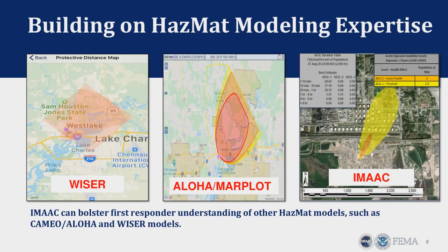And you plug that stuff into ALOHA, and ALOHA just uses a single weather observation. So you just tell it, winds from the south at 10 miles an hour. It also only has a range of about 6 miles. But the plot comes up instantly. So you put in the information you have, and you can get a plot in 10 seconds. So it's very quick. It doesn't have a long range, and it's probably best for like a small event. But it is a quick tool that's available for most first responders.